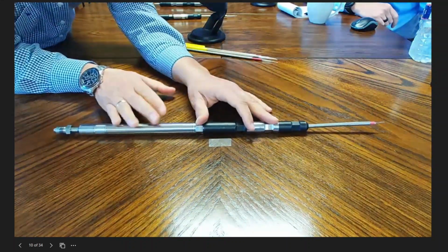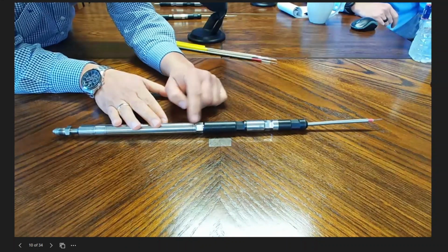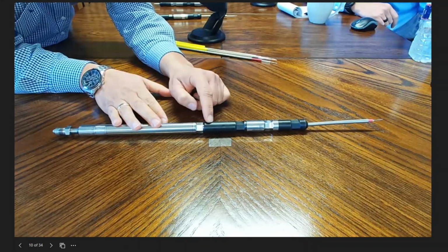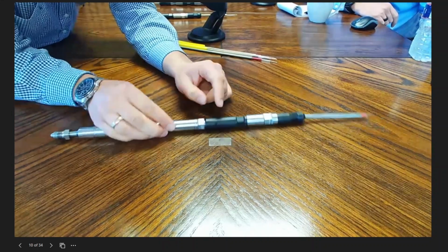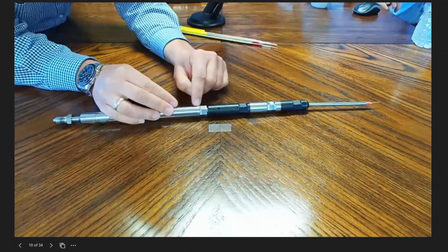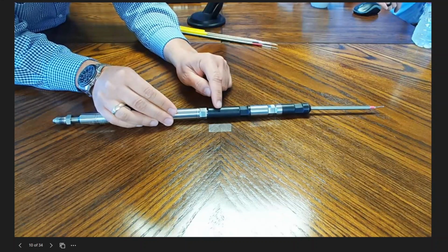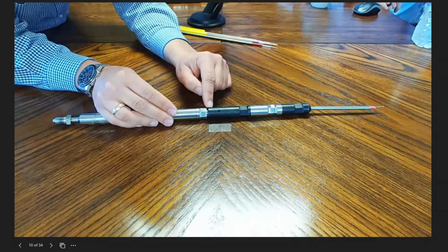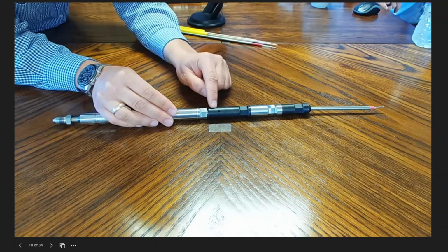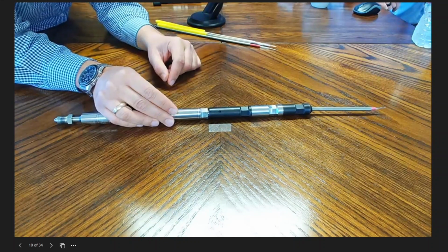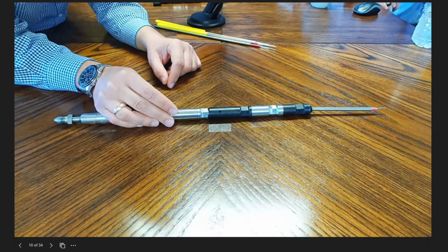Yeah. So here, then we finish, and we torque this to spec. And here you see a little hole here. Once we torque and we energize the metal seal here, we pressure test to verify integrity of the seal. Okay, so we make sure by pressure testing that the seal is doing what it's supposed to. Because you don't want to leak at that connection, because if you get any kind of water or formation fluids in there, electronics don't like fluids, right? No.